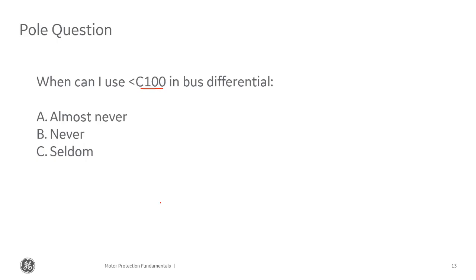So you need at least a C200, and you may not have room for a C200 or real estate. So let's talk about this high impedance module, what's inside of this thing. I've already said there's a resistor in there. So there's a resistor, the 2,000 ohm resistor. There's my 2,000 ohm resistor.